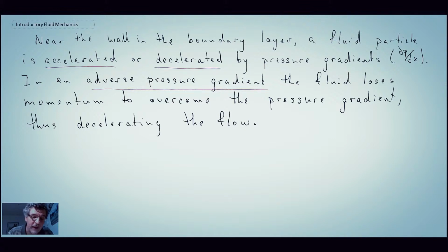It's decelerating, and you can actually get to the point where it goes to zero velocity and negative velocity. And at that point, we achieve what is called separated flow. And so the boundary layer separates. It's a very bad thing for an airfoil, for example, because that could lead to stall and then loss of lift. But for other types of flows over cylinders, we have separated flow. It happens quite often, well, all the time in bluff body flows.